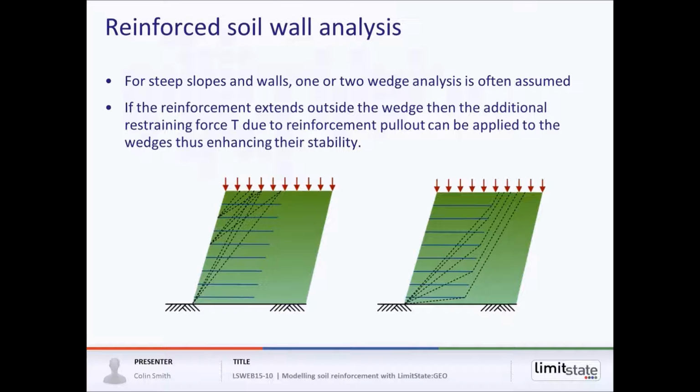For steeper slopes, or indeed as an alternative method of analysis, we can use perhaps single wedges or 2 wedges, and the principles are very similar. Rather than using a curved surface, we just use a wedge, but equally well we apply these restraining forces from the reinforcement pull-out to enhance the stability.